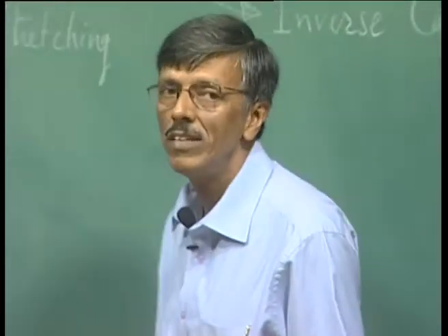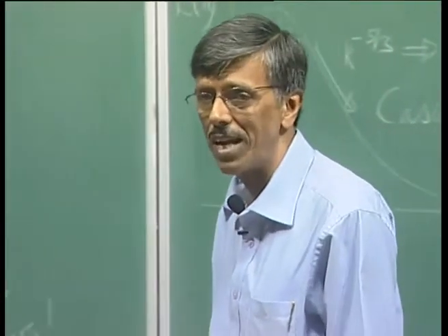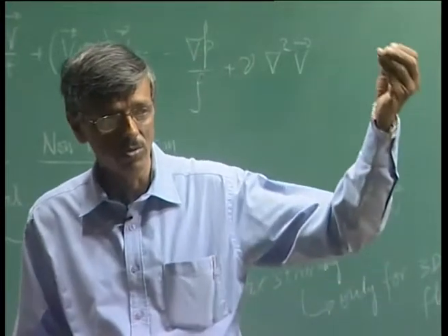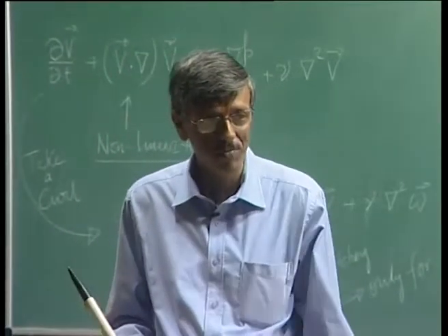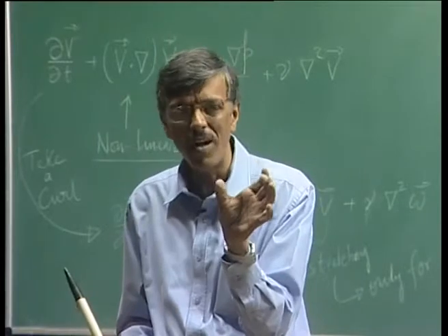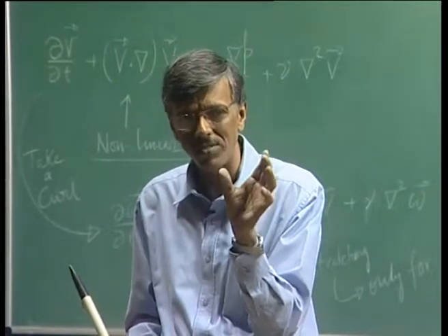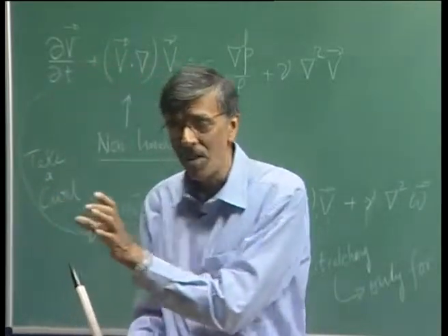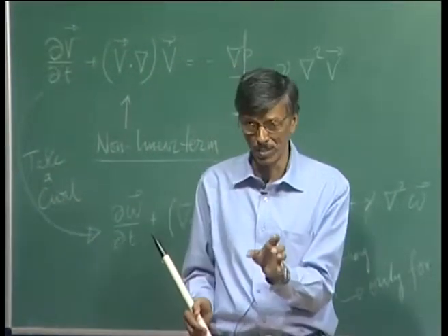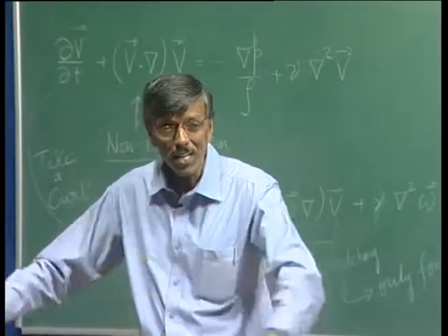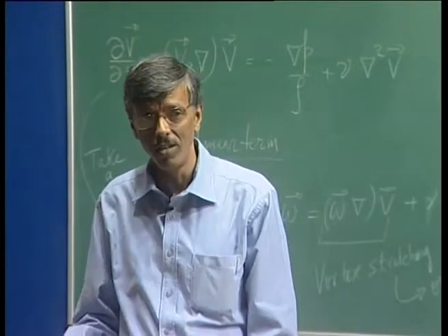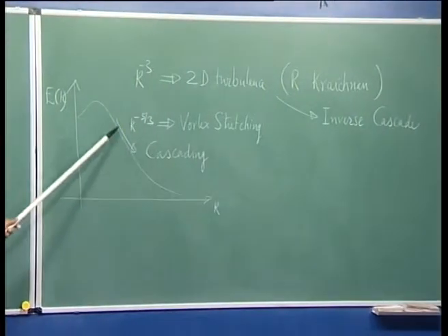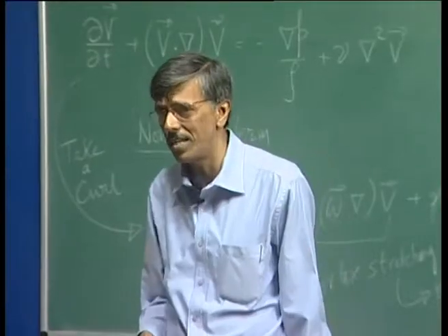We have seen dispersion is a very strong mechanism by which different scales can be created. Remember, we talked about those train of vortices going over a shear layer. So I may be defining a length scale which is given by the spacing of the successive vortices. However, because of the dispersion relation, I could create a whole host of length scales. So don't be taken up by thinking only about vortex stretching and nonlinearity.